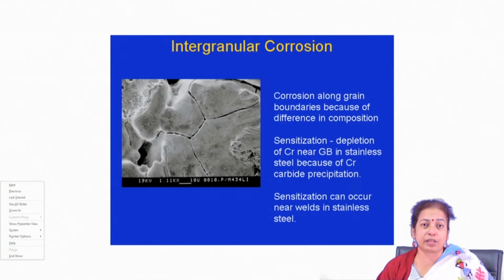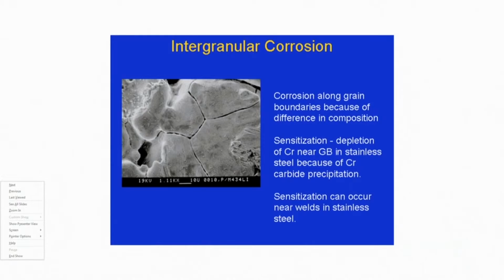This is a little different effect, because there also we find that grain boundaries are attacked at a slightly higher rate than grains, and hence grain boundaries are significant in the corrosion behavior. But what happens there is that though the initial kinetics is much higher, gradually there is formation of a very thin and highly adherent protective film, and that protective film is usually much stronger in nanostructured materials than in annealed coarse grained materials. As a result, the corrosion rate of nanostructured materials is usually lower than that of coarse grained microstructured materials.